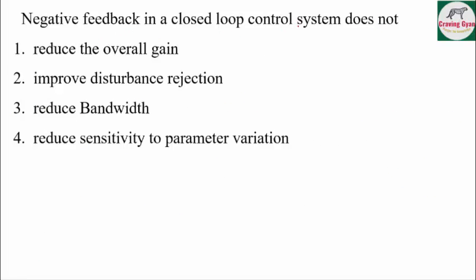Negative feedback in a closed loop system does not reduce the overall gain. It improves disturbance rejection, yes. Reduces bandwidth, yes. Reduces sensitivity to parameter variation, yes.